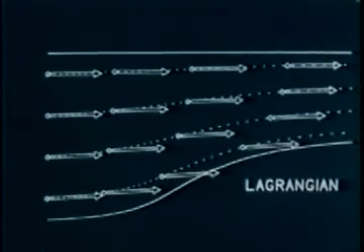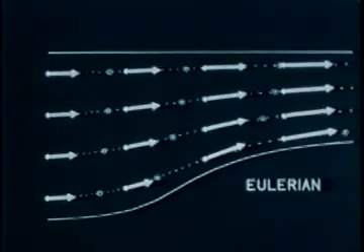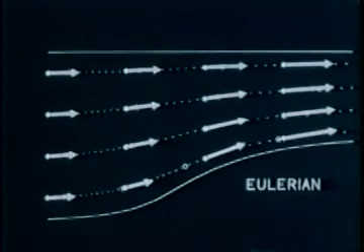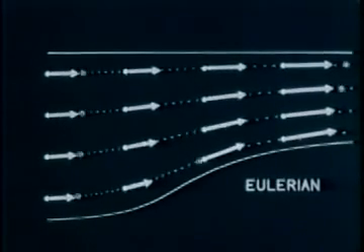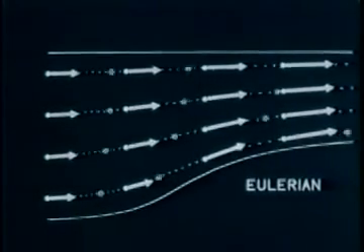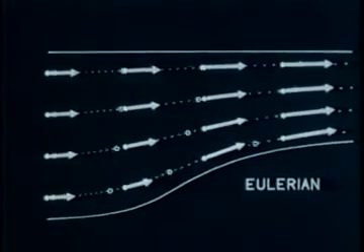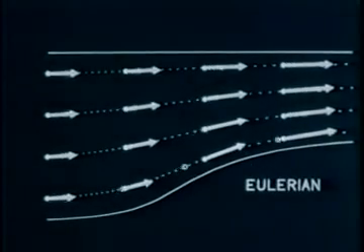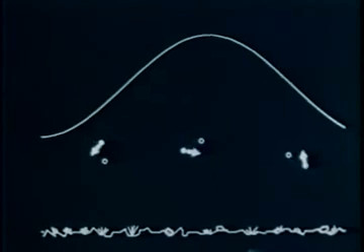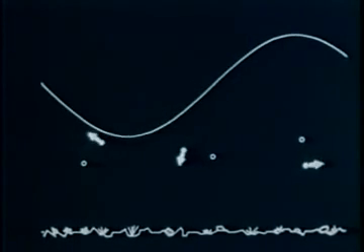This is called an Eulerian description. This has the advantage that it is sometimes possible to find a system in which the flow is steady. It is also mathematically enormously more convenient. We nearly always write the conservation equations for a continuum in this Eulerian system.